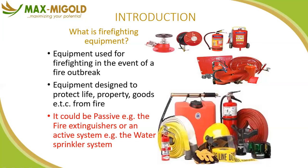I said three is fire detection and suppression, the ability to know when fire has started and the ability to actually quench that. So I give to you NFPA 13 and 72. National Fire Protection Association Standard 13 speaks to the automatic water sprinkler system, and Standard 72 of the same NFPA speaks to the fire alarming and signaling system, which is the detection, right? So we need to have this in place for us to be able to respond to fire and even quench the fire at the incipient stage.